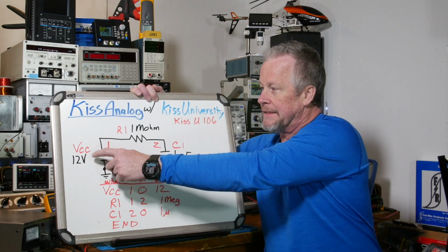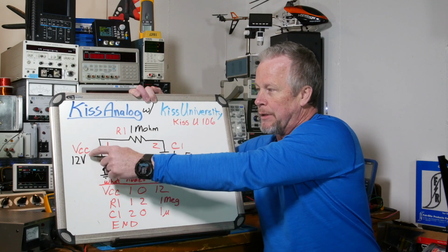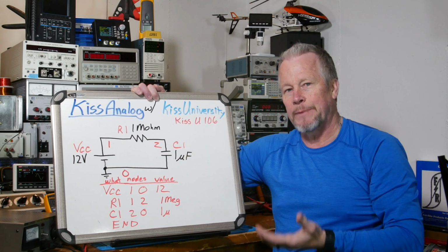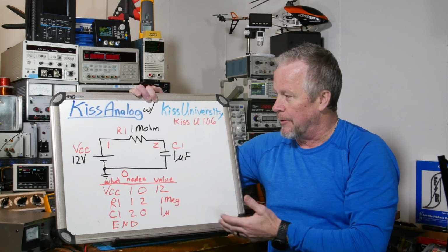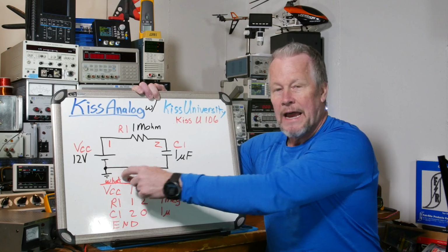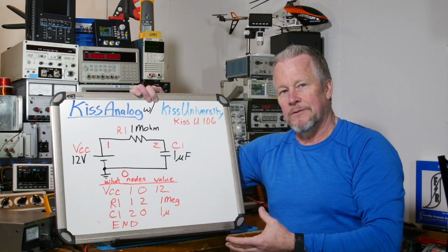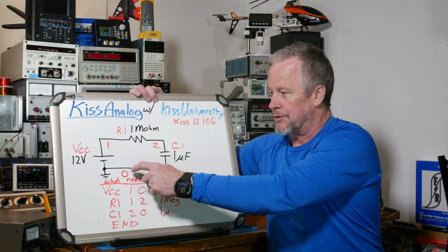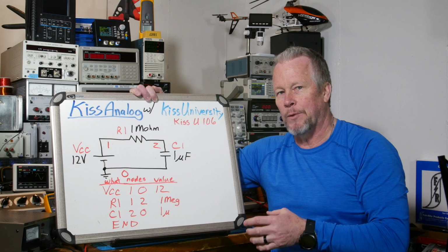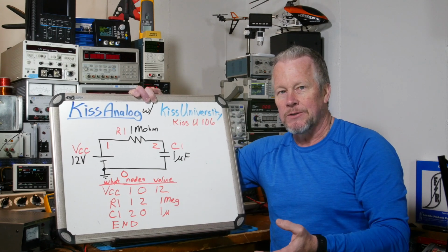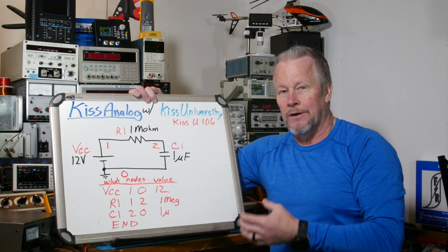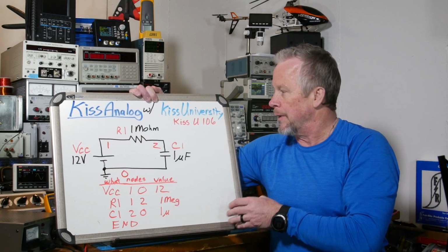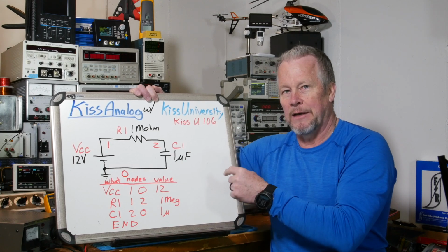The important thing is we have our elements. These are simple elements. This one starts with a V for voltage source, R for resistor, and C for capacitor. And then we also have to have a reference point, a 0 in our schematic somewhere, so that when we describe our circuit, there's always a reference point, okay? Doesn't matter where you put it really. It matters to you and your schematic and your understanding of the circuit, but to the program, it just wants to have one in there somewhere. Okay, now let me just talk a little bit more.